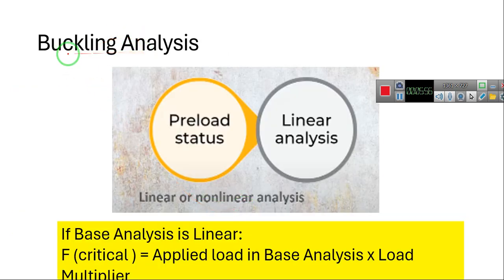Okay, the buckling analysis we perform in two steps. First we perform the preload or base analysis, which can be a linear or non-linear analysis, and then we perform the buckling analysis. And whatever load we apply in this, this is similar to the static structural analysis. We will perform the static structural analysis, and then we will add the buckling analysis.